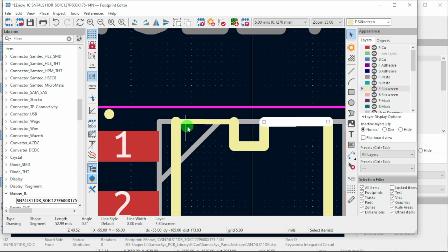Minimum through hole, that's saying about 12 and 10. And this I'm gonna change. Minimum via diameter 20. Minimum copper to hole clearance 10. Copper edge clearance 20. I think I have 15 in another reference, so okay, I have everything set up here.